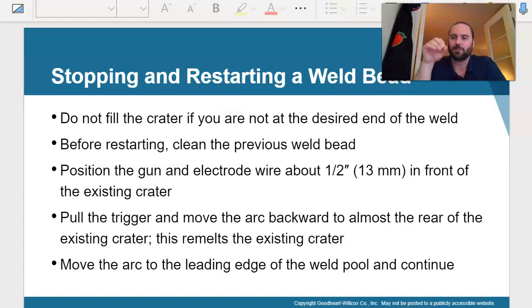Again, that would be more for your solid wire. For flux core, I would never recommend going back and forward. Once you pull that trigger, you create your arc, create your puddle, move that puddle across the joint. Don't ever come back. Once you come back with anything that has flux in it, slag inclusion is going to be your biggest problem. You don't want to be going back and forth. It's the same way with stick welding, and I think the book tells you the same thing with stick. I'm telling you from my experience, if it has flux, don't ever go back and then forward again. With MIG and solid wire, it's different. It doesn't have that, so you don't have to worry about slag inclusion, is the big thing.